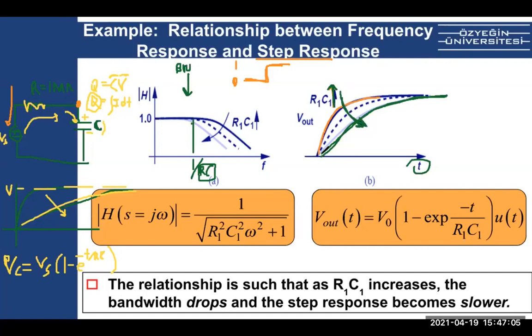That means it will take forever to go through digital circuits. You have a bunch of digital circuits, AND gates, NOR gates, and so on, right? So you apply an input, and it will take forever to charge and discharge these intermediate nodes. So a good circuit is a fast circuit. A fast circuit means RC is small, both R and C, right? R is small, C is small. Then when you apply a digital 0, 1, instead of this, you'll see this, right? You won't see that charging mechanism. You'll just instantly see the output.